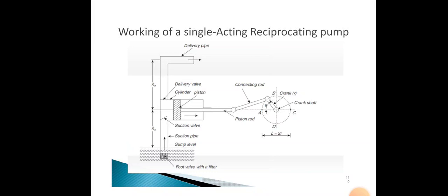The reciprocating pump is a device that converts mechanical energy into hydraulic energy by sucking the liquid into a cylinder. In this pump, a piston reciprocates, which exerts thrust on the liquid and increases its hydraulic energy. A reciprocating pump is also known as a positive displacement pump because it discharges a definite quantity of liquid. It is often used where a small quantity of liquid is to be handled and where the delivery pressure is quite significant.